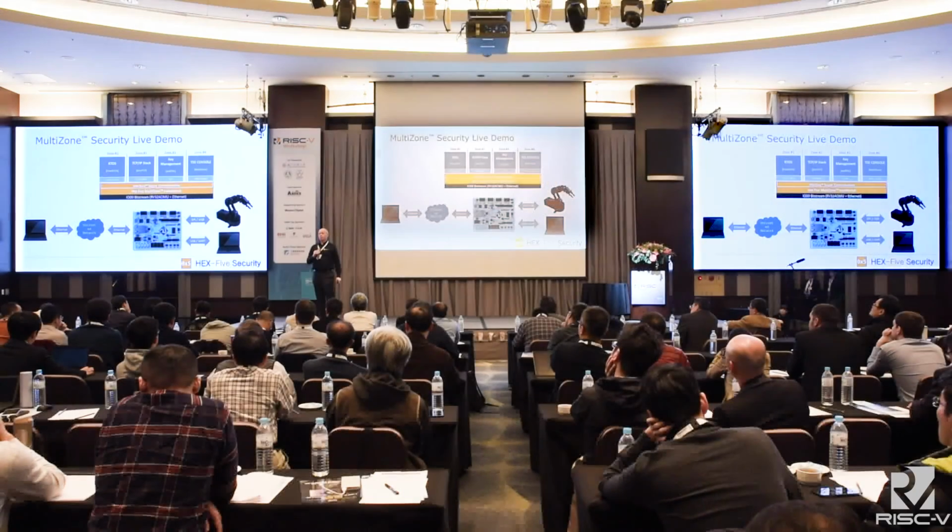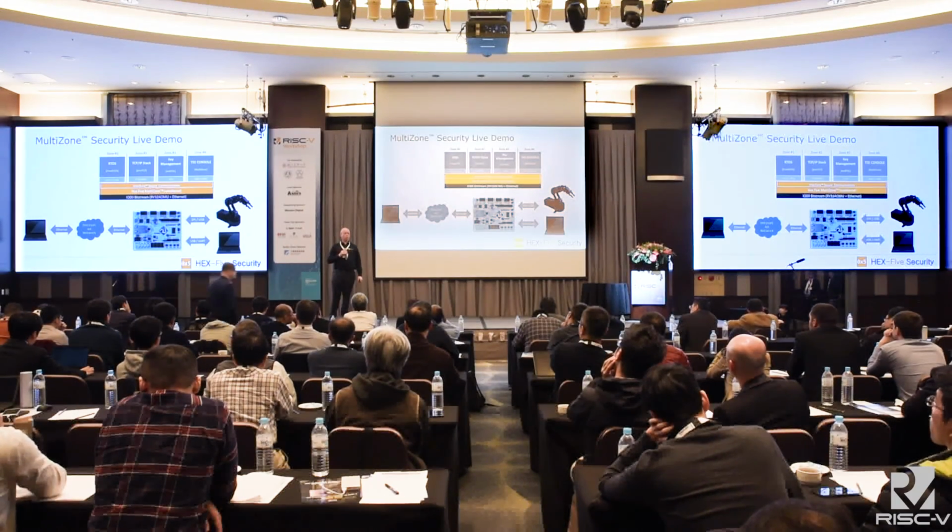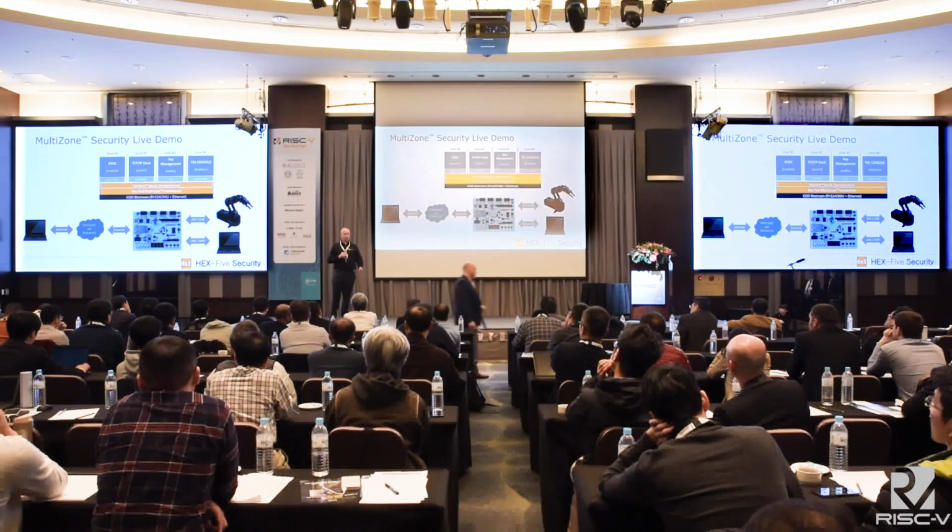What do we need to know about the SoC in order to build a secure platform? I think this is something that is developing inside the foundation, that there's a need to do more than just secure the core and more than just worry about the core. There is a developing effort that I think Palmer's actually leading in order to develop a larger specification around securing the platform. But in the end, each platform will be different. It'll have different peripherals, it'll have different memory maps. So the system, the bootloader, has to be structured around that. We can't abstract this entirely away and keep it small size. So much like most things in engineering, there's no free lunch here. Here the focus is on building something small and secure, which means there is some customization that's necessary to each SoC platform.